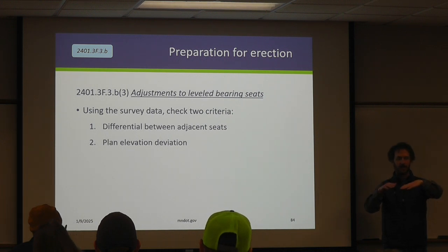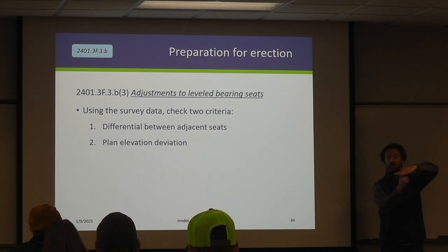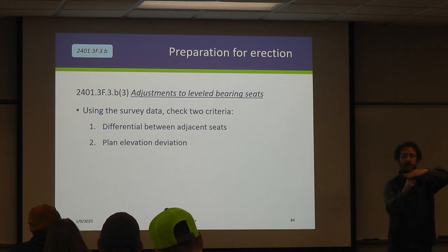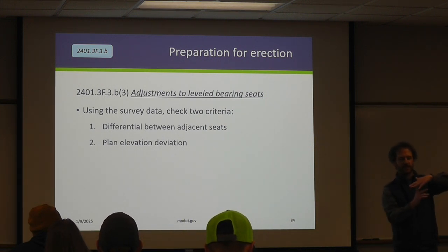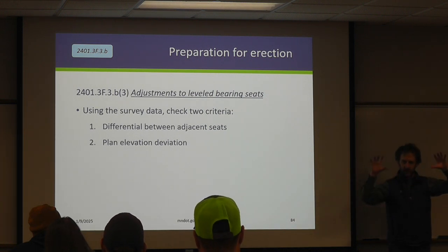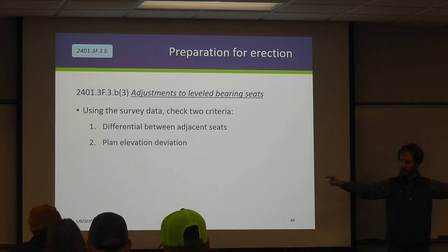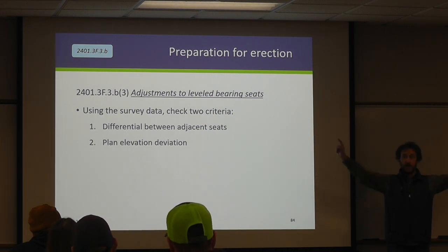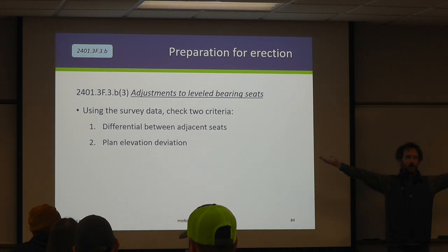Now, if you think about having everything supposed to be set like this, but then you have one bump. Did your system get fabricated with that one bump in mind? No. I've seen a job, it was a steel bridge where we had really stiff diaphragms. And we had something like that, where you had one seat that was sticking up a little bit higher. Those diaphragms were so rigid that it picked up not only the next two beams, but then even farther away. So one girder was holding 4 other beams up.